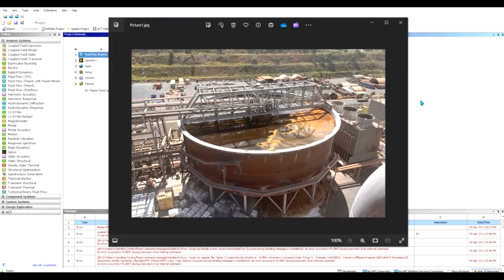This video is going to do a quick introduction into how the CFD simulations were performed for this thesis study using ANSYS Fluent. To give a quick summary, we have this settler tank, this spent litter settler tank, with incoming spent litter flowing into the central feed well, and we're going to simulate that spent litter both surging through the bottom of the feed well and into the rest of the outer tank area, and sloshing over the top of the feed well to investigate what sort of wave propagation occurs from this resonant inlet pumping.